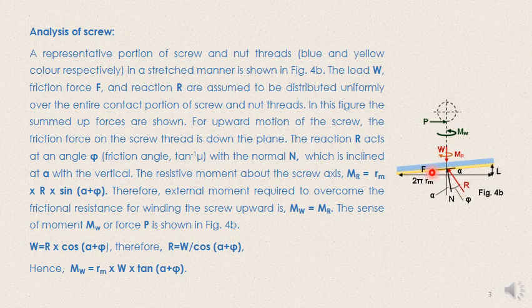This R is the resultant of friction force and normal force. Although I have shown the nature of the friction force and the normal force, for analysis I will be considering R only. The representation is just for your visual idea of how the resultant force occurs.